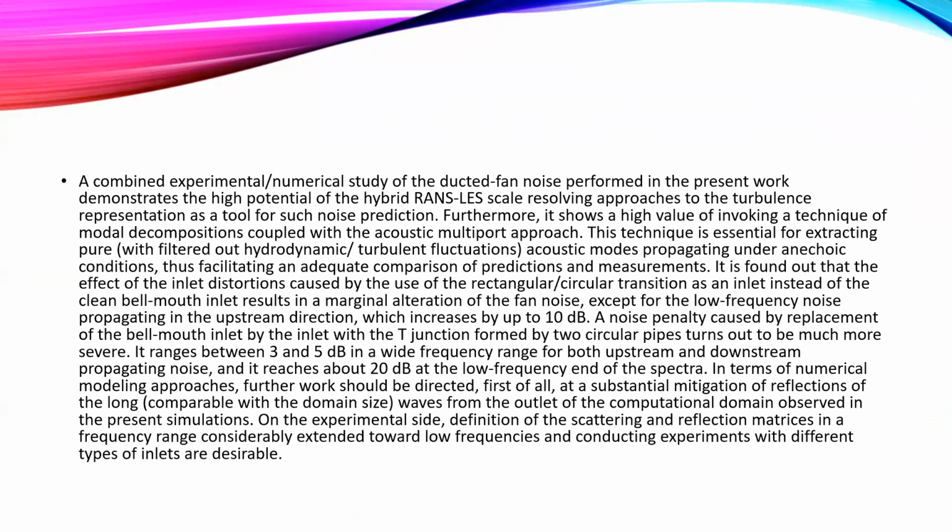A combined experimental and numerical study of a ducted fan was performed to demonstrate the high potential of hybrid methods, with the exception of low frequency noise propagating in the upstream direction, which increases by up to 10 dB. On the experiment side, the definition of scattering and reflection matrices shows the high value of invoking techniques of modal decomposition.